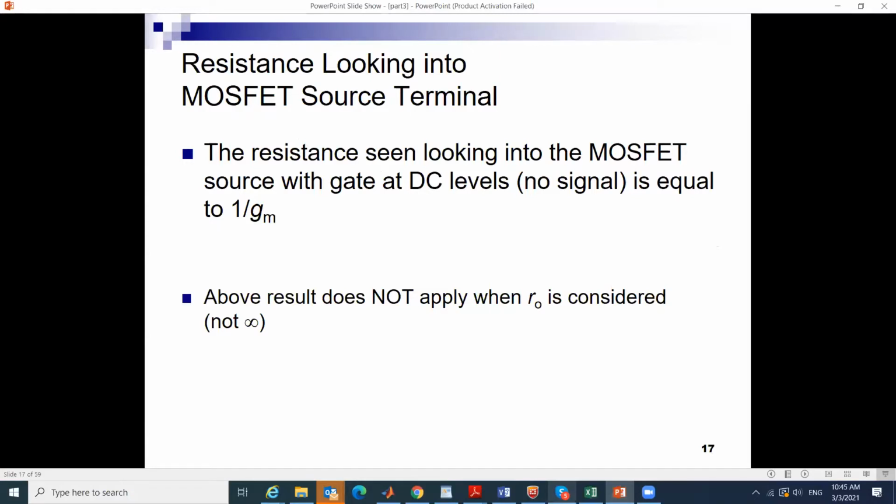Now the input resistance we already went over on the sheet, we said it is 1 over gm, and this is counting for me the rule to tell me that looking up from here if I have RD. Okay, I have two cases. One case which is it is equal to 1 over gm if ro is infinite, else it is equal to RD over ro over 1 plus gm ro. This comes out of the rule which we just saw. And let me double check the equation so that I don't memorize it wrong.